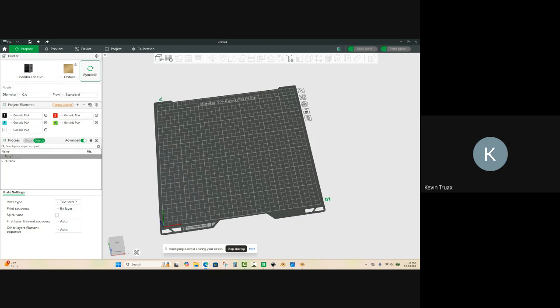And there is one big thing that you want to be mindful of. When you import a Tinkercad model into Bamboo and you do any type of Boolean operation after the fact, you will lose all coloring information. If you changed colors of anything, whether painting it or changing the colors here in the Objects tab, you will lose all color information. Now, if we build the model in Bamboo and do a Boolean operation, then no, we could do all kinds of Boolean operations and never lose the coloring that we already have accomplished.